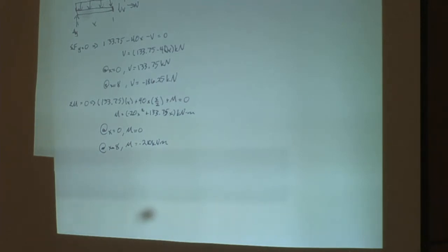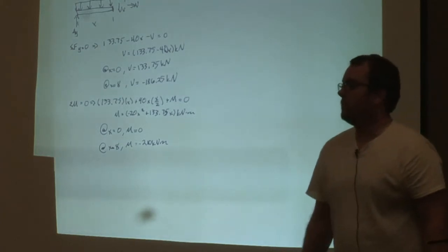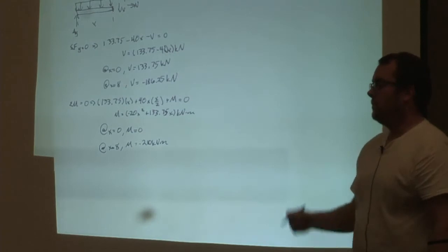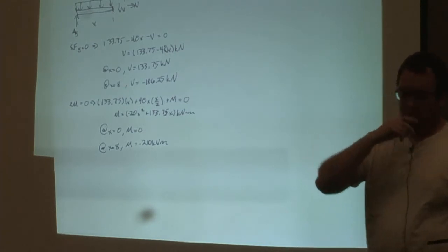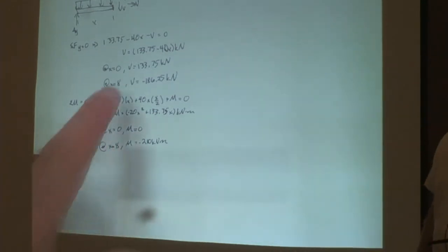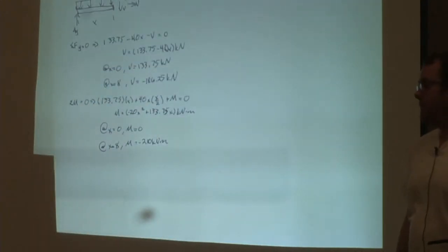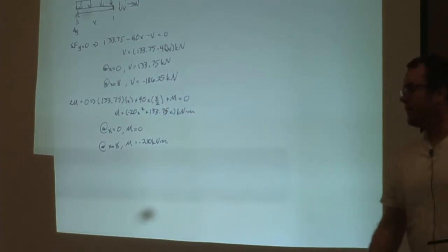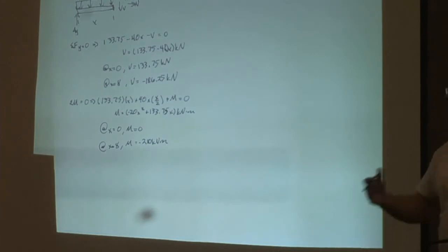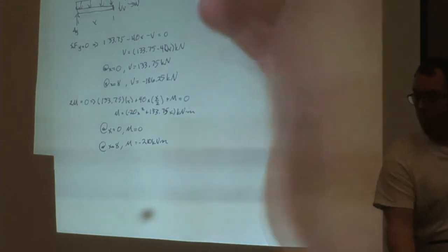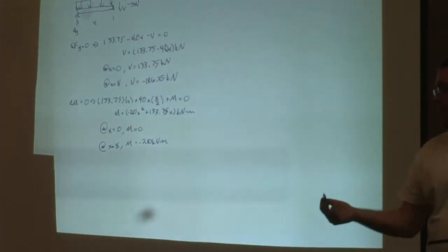If the shear force is variable, like it changes based on where you make the cut, why did we pick 133.75 to be the shear? It's just halfway through it. It was just easy to calculate. You're going to start doing intuition-based stuff from here on out in the engineering classes. So just try to make it easier on yourself when you choose where to do certain things. Because it really doesn't matter where we cut it. It's just the ease of the math of where we cut it. Does that make sense? It makes sense.